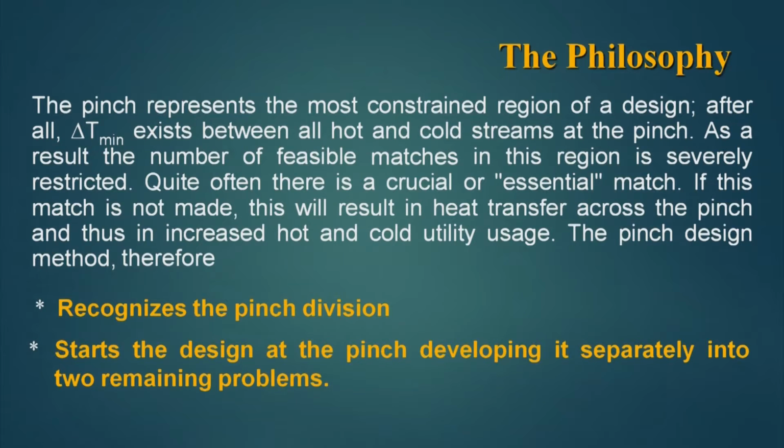The other rule is to start the design at the pinch, developing it separately into the two remaining problems. So, design will be started at the point where the problem is most restricted, and then the method is to go away from the pinch, because when we go away from the pinch, the delta T increases.